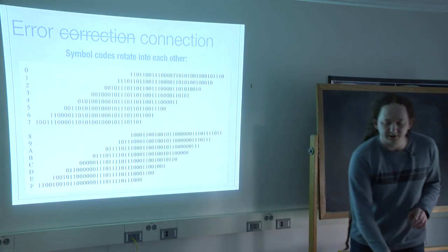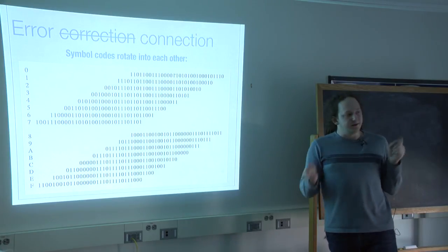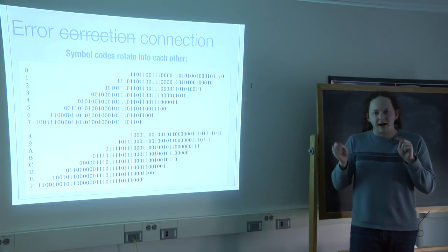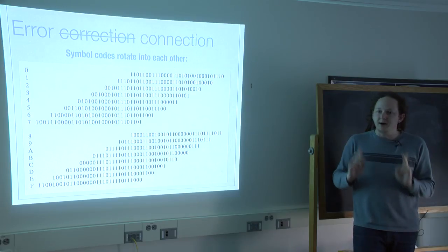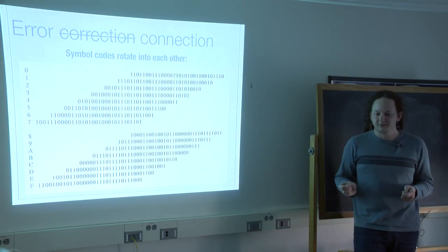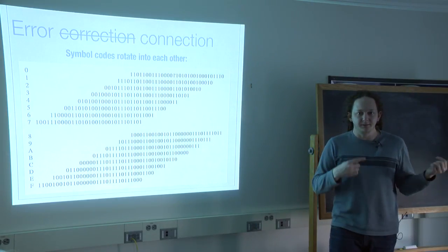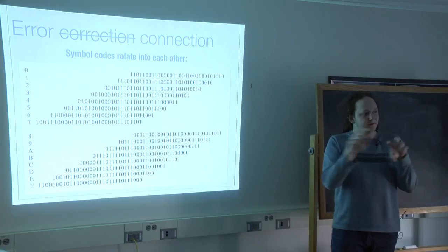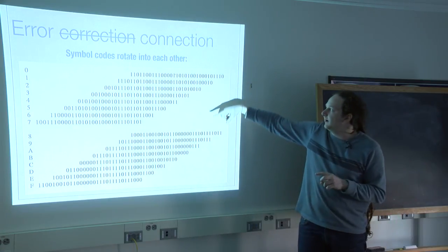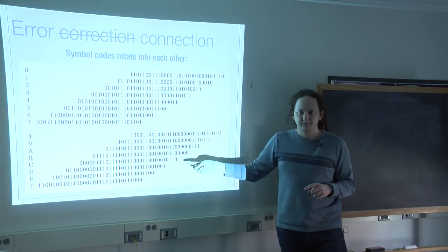So what I'm trying to do now is to not inject a perfectly valid frame, but instead inject something that at layer 1 looks close enough to a valid frame that the receiver doesn't care about the difference. So I built the papercraft game that I showed you the picture of earlier, and I shifted the things around on paper until I saw the 2 rings. And as you go down any one of these columns, all of the bits are the same.